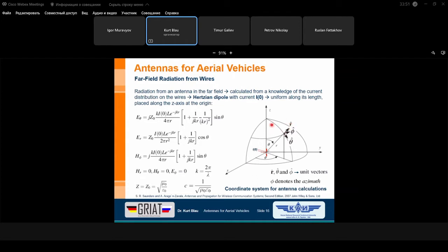Then we can see that in the theta direction, this part here, we have an E-field component. And, for instance, in the r direction, this is here E_r, in the direction of propagation, we also have an E-field component, but this is very, very small. And the larger the distance from the region, the more we can see this component as non-existent or negligible.